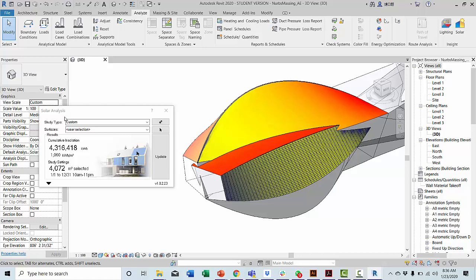Okay. So at this point, let's say that I choose this one from all my masses because it's the one that behaved the best. And then I add materials and I start working with the materials in order to get a better result on it. Okay? And an added advantage of working with the masses, like we saw from the workshop, right? You can go back and modify those masses and then update the faces so all your materials update as well. Yeah, so you don't have to change or eliminate the wall, put it again, or create a different mass. You just modify the mass and you just update it.